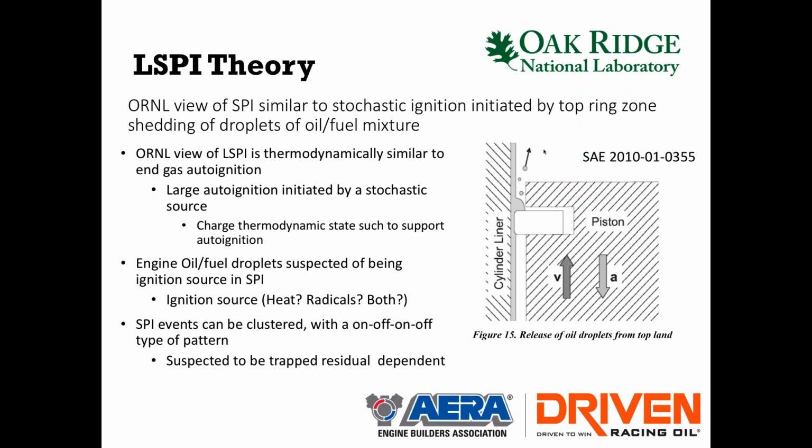So there is a definite theory about the transportation of the oil up into the combustion chamber, and the mixing of the oil and the fuel in the combustion chamber is certainly an issue. The last line on that slide is really key. They really started to focus on the suspicion that it's the trapped residual, which they mean trapped residual unburnt, unvaporized fuel in the residual exhaust, was a contributing factor.